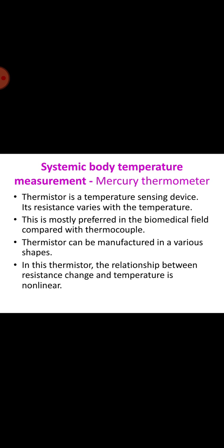Negative temperature coefficient (NTC) thermistors' resistance decreases as the temperature increases, while PTC, that is positive temperature coefficient thermistors' resistance, increases as the temperature increases. So only NTC thermistors are commonly used in temperature measurement. And the thermistors are available with a variety of base resistance and resistance versus temperature curves.